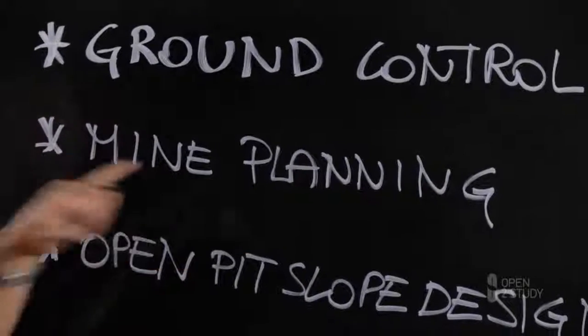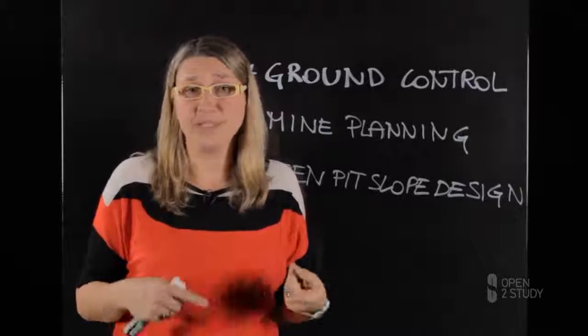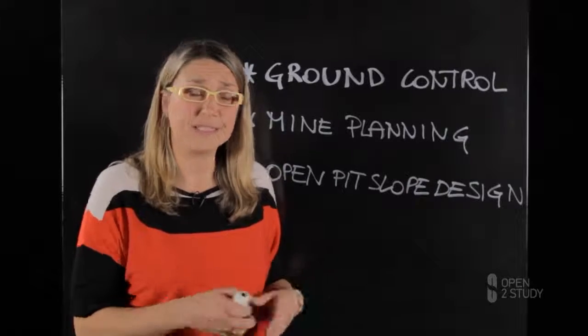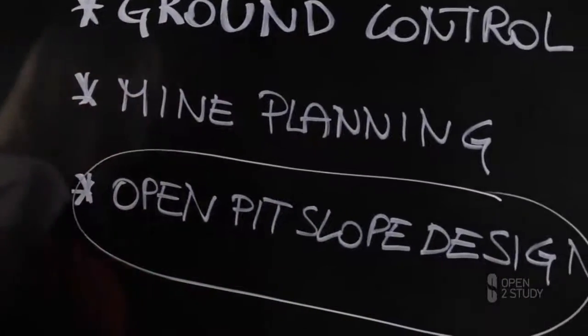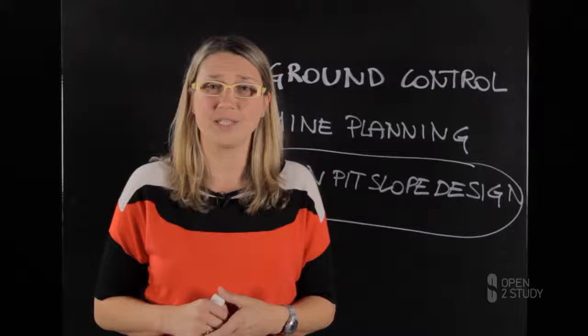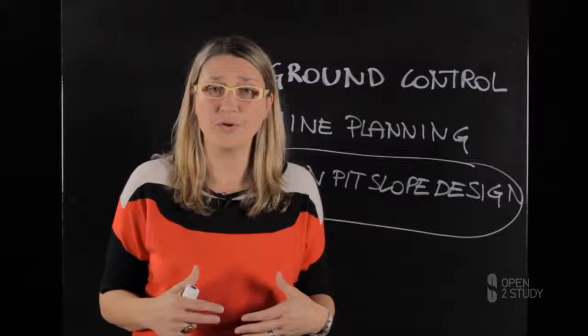The mine planning process involves much more engineering studies, including the development, the construction, and the exploitation of the mine site. It is at this phase that open pit slope design comes in. The slope design has the main objective to enable a safe and economic design for benches, ramps, inter-ramps, pit walls, and the overall slope scale. The slope stability process involves slope stability analysis for intact rock, rock masses, and also waste or spoil material.